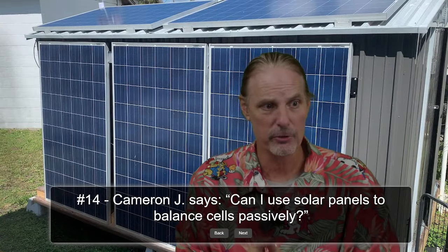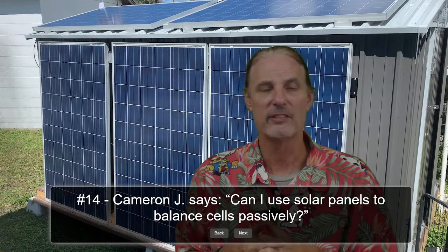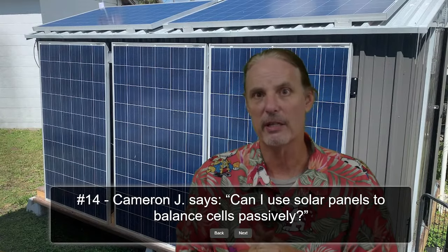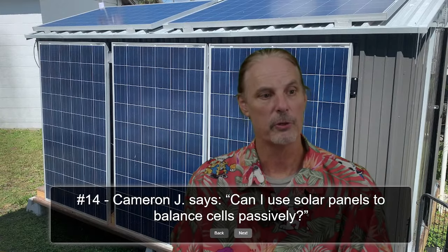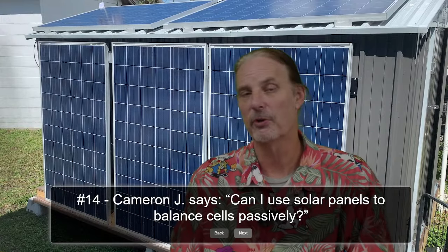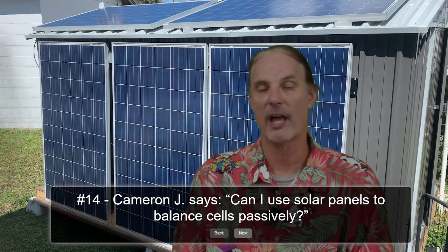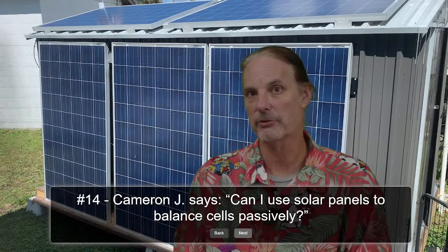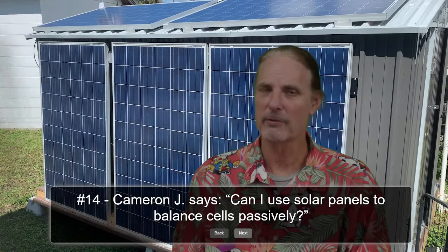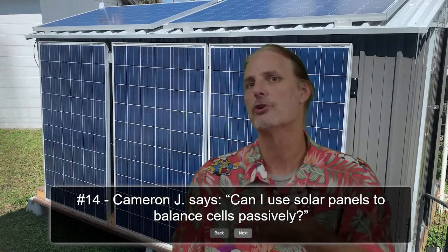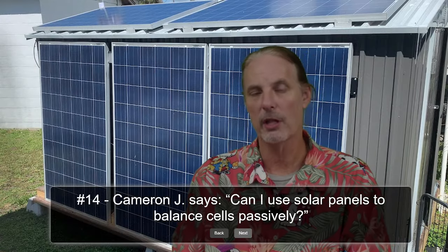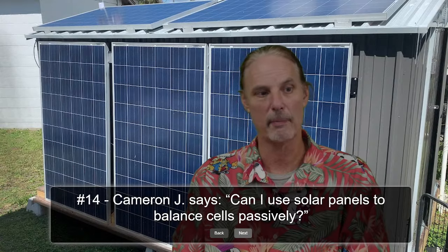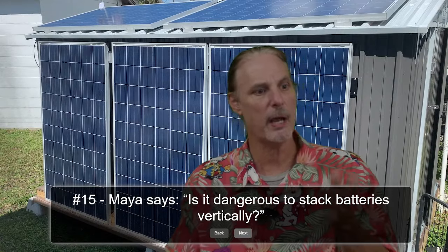In a case of passive, as Cameron's talking about here, that definitely is the way it would work, Cameron, is new voltage would replace the voltage that you burn off in heat as opposed to transferring it from one cell to another. So yes, you can, and that is the preferred way of doing it. That's how EG4's LifePower batteries work. They are passive balancers, and I don't know if they have any plans with newer versions to change that to active balancers or whatnot, but I know that the version 1 LifePower4 EG4 batteries were definitely passive.